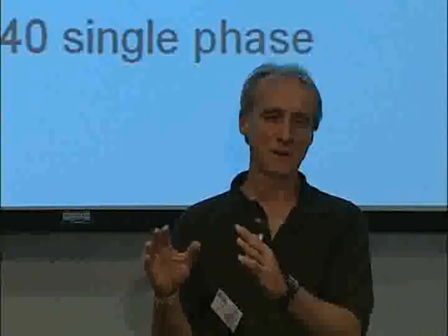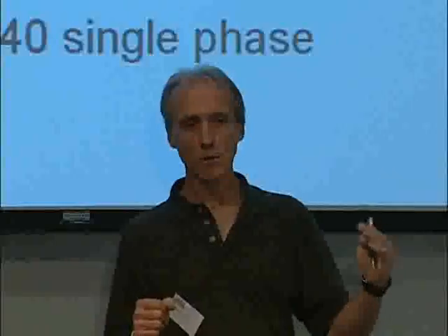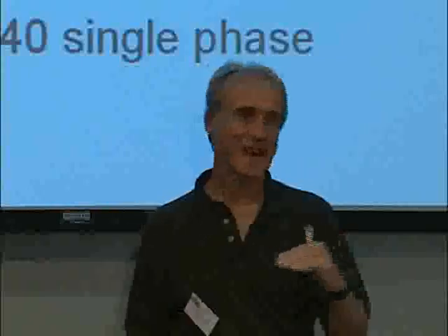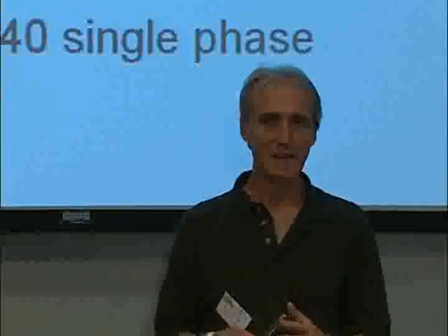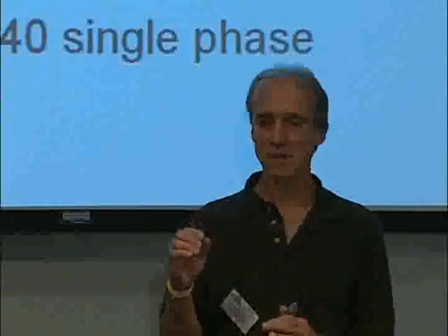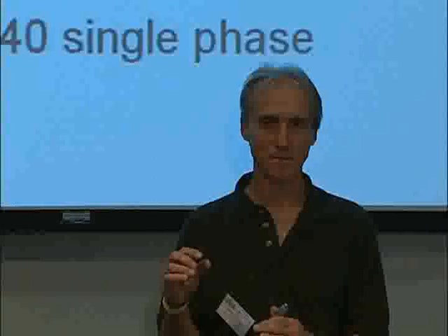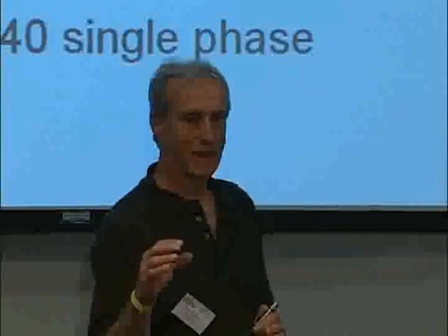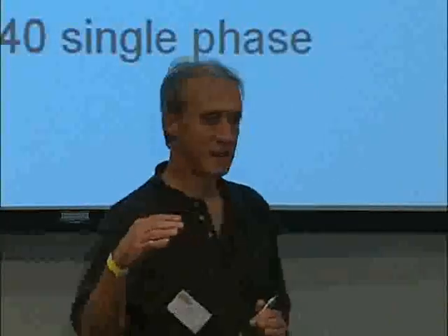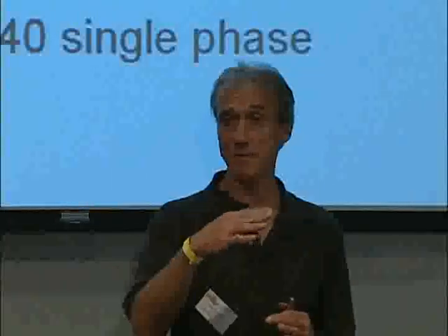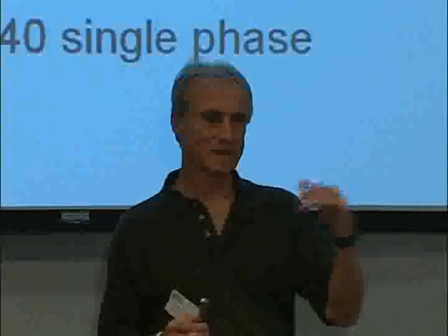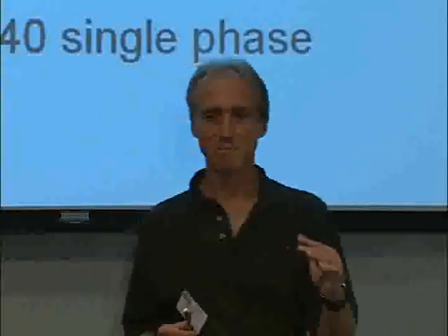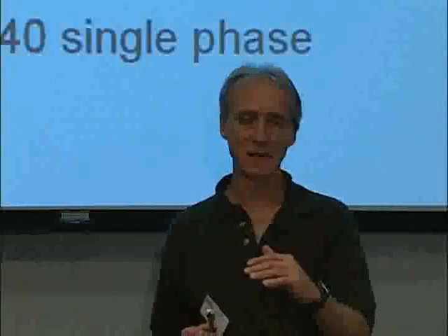And when it's sure that it has it all synchronized, then it will turn on, take the solar power, and start sending it out exactly as the power company is coming in. It has to match the voltage, and it has to match the frequency within a very narrow band, like 5 or 10%. The power company's voltage has to be within that 5 or 10% range of the inverter. If it has that, then it'll start sending power out. And it checks that many times a second during its entire operation.